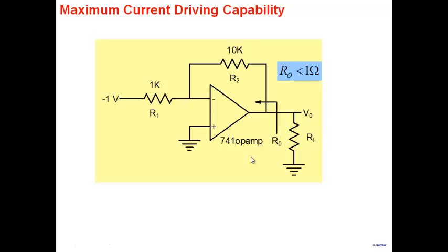Now, in light of what we have just discussed about amplifiers and output resistance, if I connect a resistance RL here of whether 1K or 10K, does it really matter? For what value of RL do you think my output will begin to get affected?